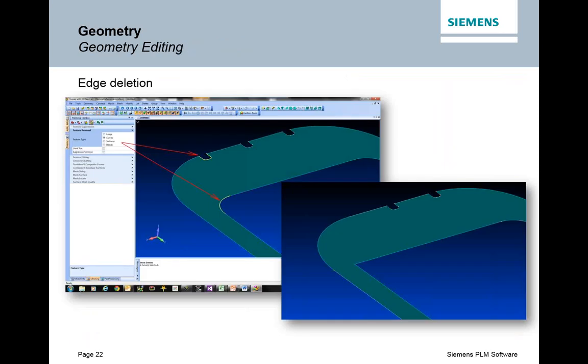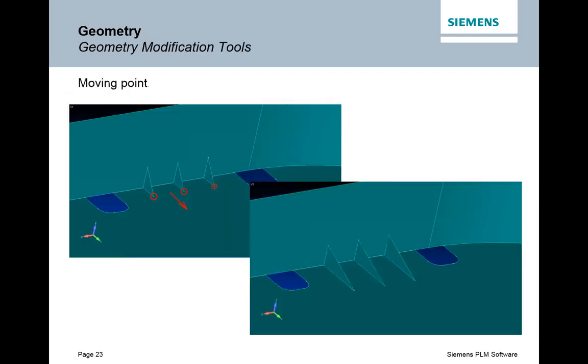Some of my favorites in 11.2 are coming up here. This is the start of some surface editing that they've improved upon. Right here they're showing how you can delete some edges on surfaces now with the feature removal tool, and that will eliminate those features from the surface.